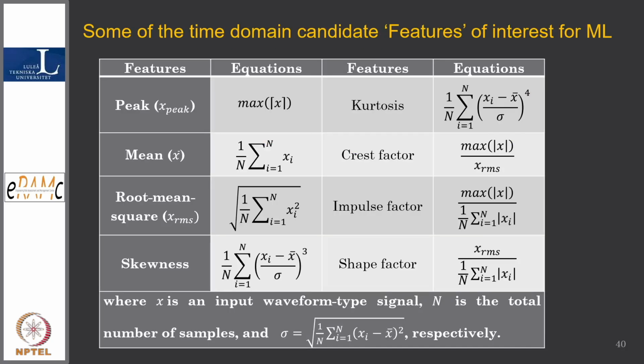As I said, feature extraction. For a problem, what are the features you might think are required? If I feed all the data, it becomes too bulky. But suppose I want to understand the characteristics of the population, I'll first go for, let us say, the mean. What is the mean of the population? That will be one node: the mean is 1/n times the addition from 1 to n. And then crest factor, which is about its height, so we get the maximum and the RMS value, and we have an equation for this.